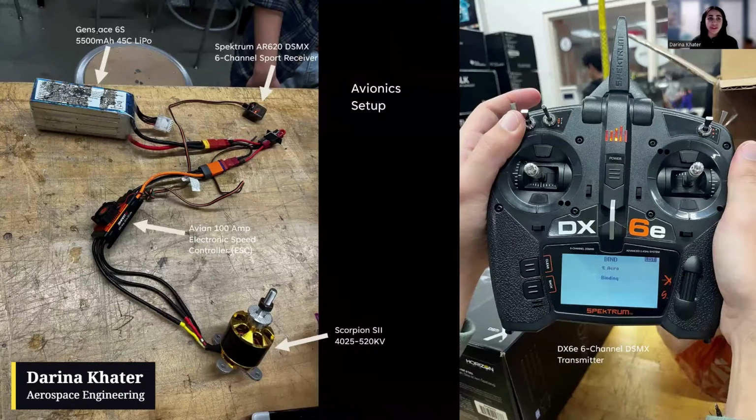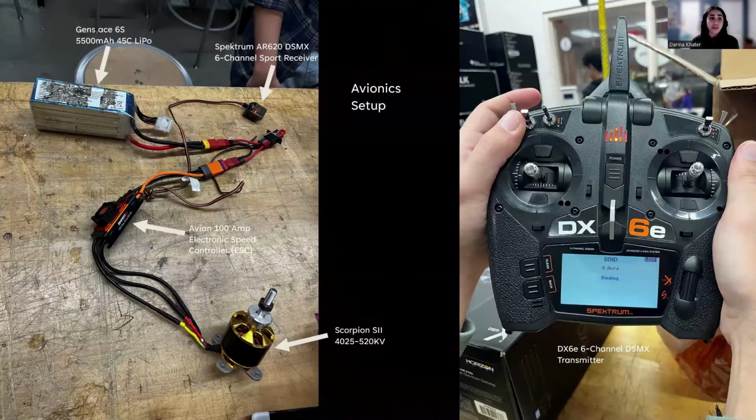Through researching motors that meet the needs of our UAV, we selected the motor shown on the slide. We then selected a 6S LiPo battery and a 100 amp electronic speed controller. We used five 9G microservos to adjust the control surfaces, one for each aileron, one for each rudder, and one for the elevator. The ESC, along with the five servos, were all connected to the receiver to allow for wireless